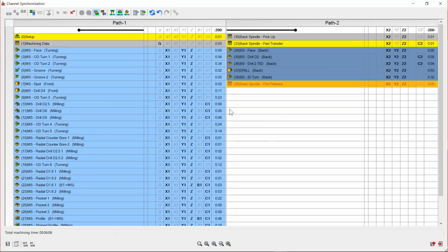If I leave everything like it is here, I will just show you a little bit of what is inside the interface, and then we'll go forward to show you how the simulation works and the G-code. So on the top left, we do have a synchronized select operation start to start, and I can pretty much represent what is going to happen. Basically, it will take two operations, and the wait mark will be inserted before that. Then we have one after each other, and then it will end together. So it's like operations end to end.